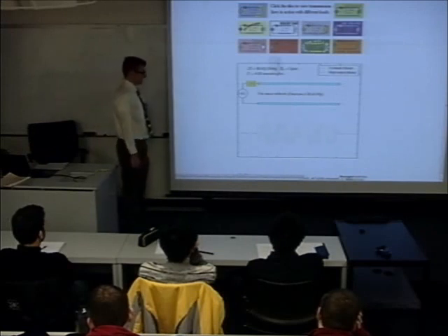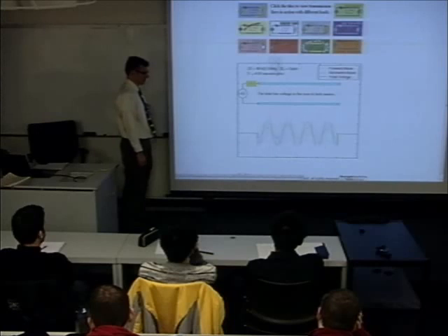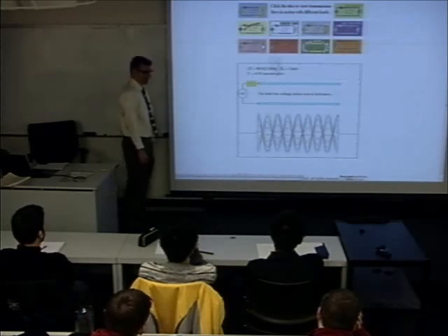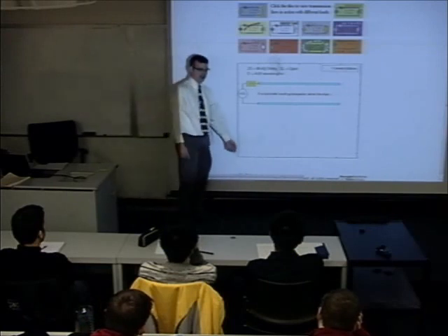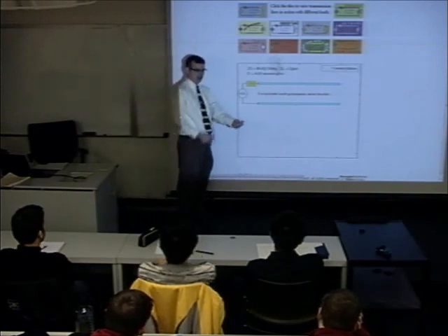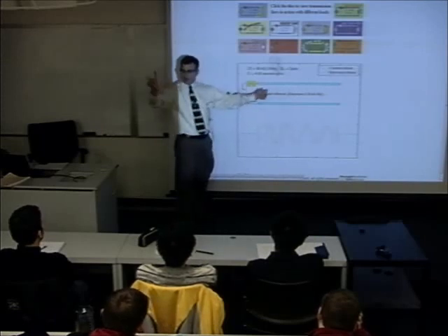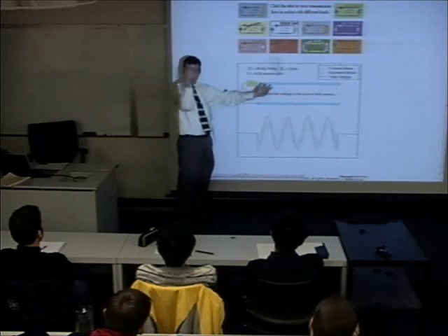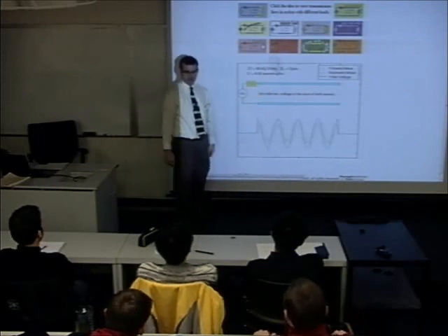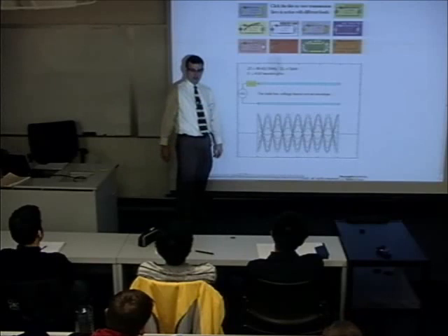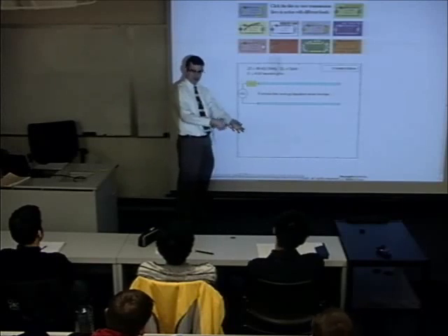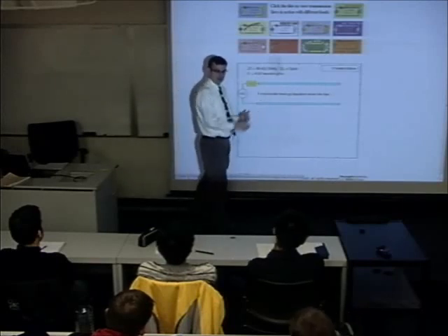There's the backwards propagating wave. Notice it's the exact same amplitude as the forward propagating wave because there's no place for it to go. And you get a standing wave, which is exactly what you did in that physics experiment when your high school teacher took a piece of string, held it taut, and then wiggled it up and down. The mechanical wave went down, reflected back with a magnitude 1 reflection coefficient, and made that same standing wave pattern so that there were nulls at certain points of space and peaks at other points of space.